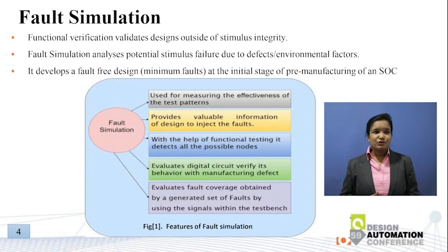Fault simulation is used to replicate the typical sources of failure and analyze them using EDA tools. It includes a testing structure using different fault simulation algorithms, and these algorithms help us to gain insight into a functional design and ensure maximum coverage quality testing.